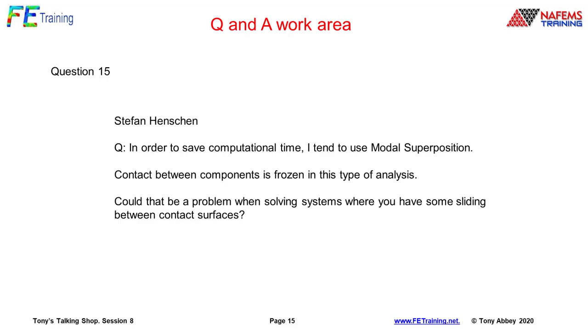What I've done then is to say where I think there's some softening of the connection between the components, put in linear springs, which would to some extent allow you to have that change in frequency I talked about for something oscillating in a slot. If we don't have the edges of the slot, it's just a free oscillation.